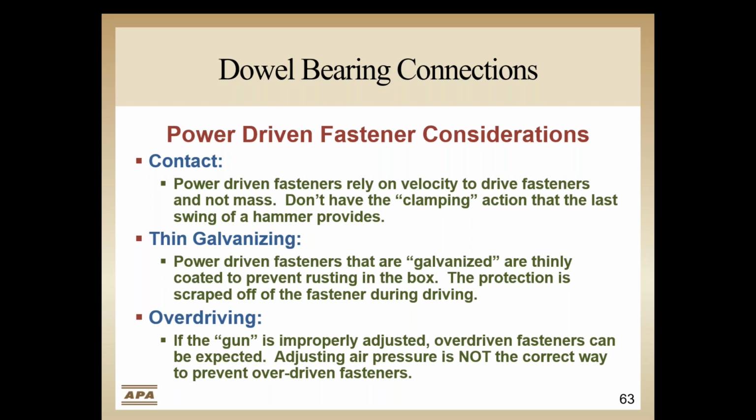We should also consider that power-driven nails generally have thin galvanizing that may scrape off when driving the nail, which can lead to rust if exposed, so they should be covered relatively quickly. Lastly, one of the most common concerns is overdriving nails. There is a correct way to adjust the nailers to ensure the nail is driven properly and consistently. It is not to increase or decrease the nail pressure on the nailer.